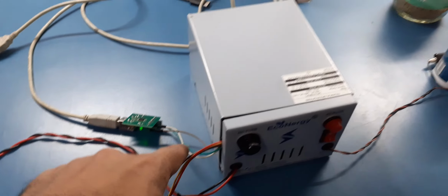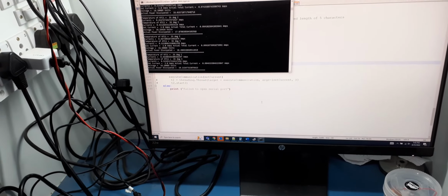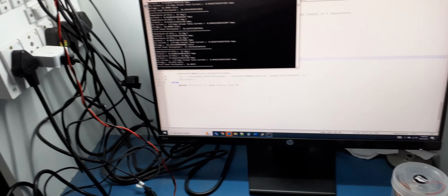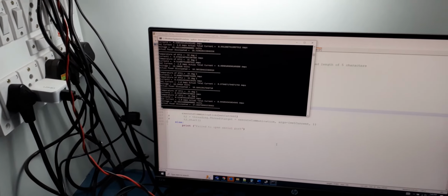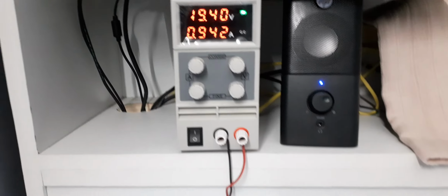So these are the three different modes in which this electronic load can be configured, and the configuration is through the serial port and by a Python script. And obviously the data logging happens, so I can measure the current, voltage and transient response. Everything can be monitored and plotted over Python on the computer. So that's all.